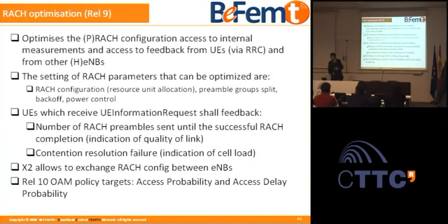Another one is the radio access channel. Now that's a very important one. It's a feature which runs through the whole 3GPP family. UMTS had it, it was really important. LTE has it, it's really important. What is a radio access channel? A radio access channel is a channel you use to say, hello, I'm here, I want to establish a call. So it's an uplink channel.